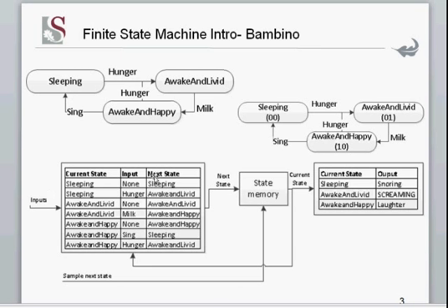So on the left-hand side here, we can see that we have some inputs, and one of the inputs into this block, which determines what will be the next state, is the present state. So the present state, as well as the inputs, determine what the next state will be. Then we also use memory here to remember what state we're in, and we use some block again to determine what the output will be, and this depends on the present state.